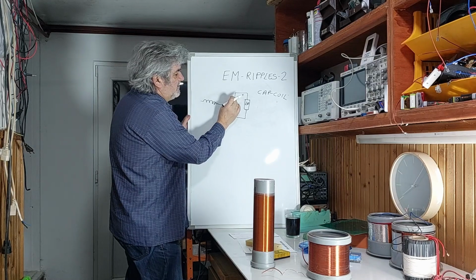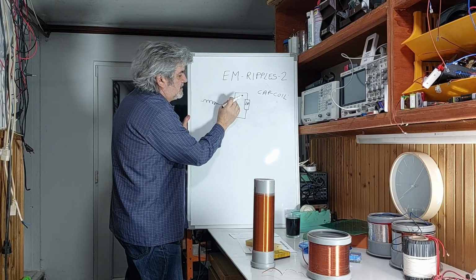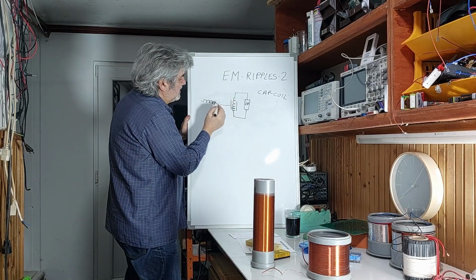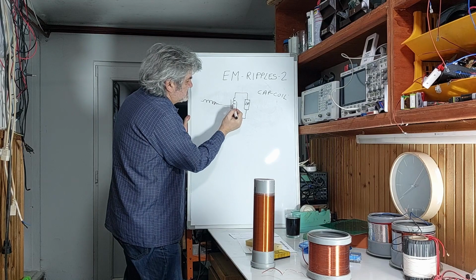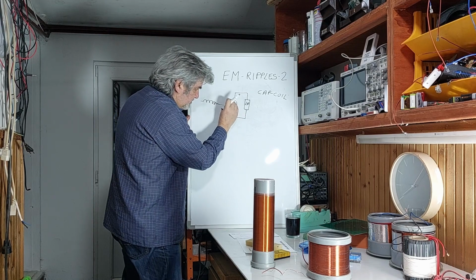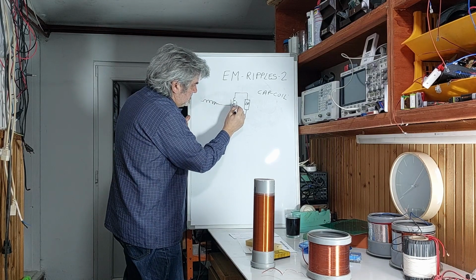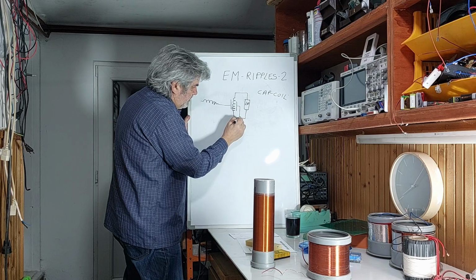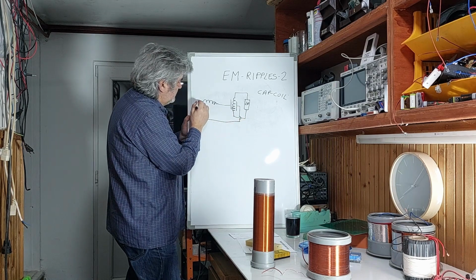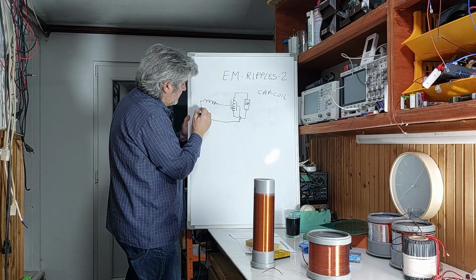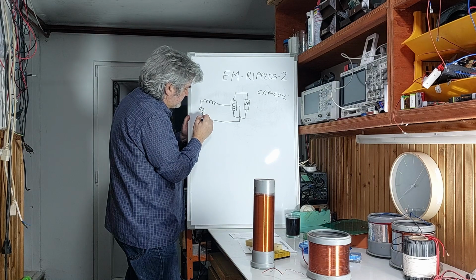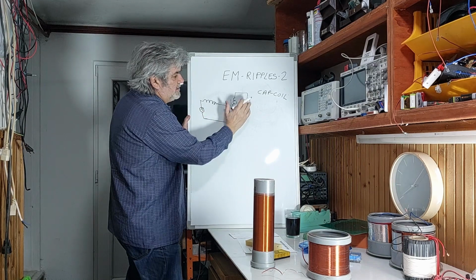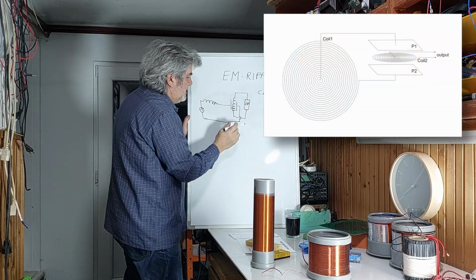So this one will act like a capacitor, and when I get resonance with this total capacitance, I will have higher current from the source and the best work.